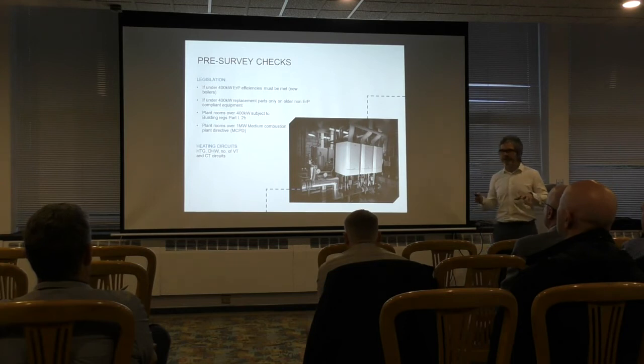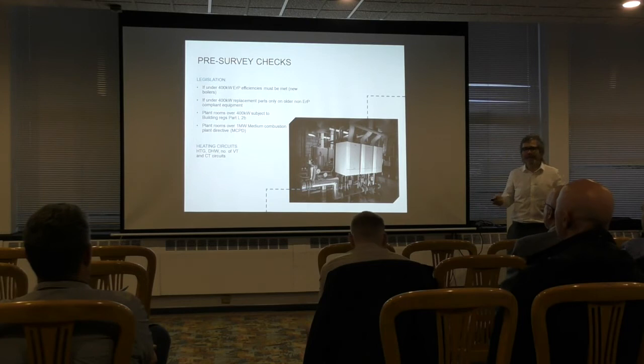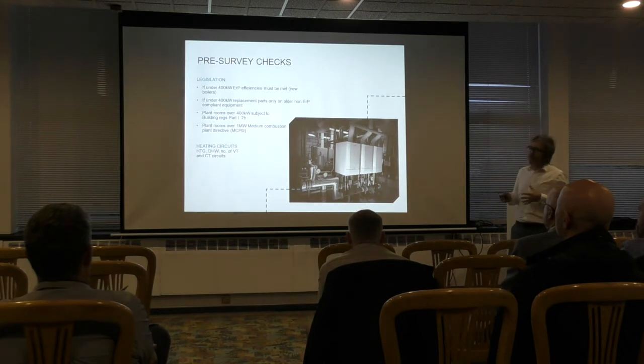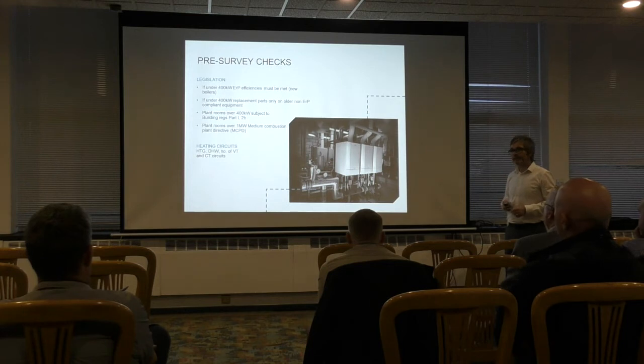Are you all familiar with ERP? Have you heard of ERP? If you don't know what ERP is, it stands for Energy Related Products. It was introduced really to the commercial market in September 2015. What it was basically saying is that any boiler under 400 kilowatts had to meet a certain efficiency. I can't remember exactly what it is, it's about 92.5% efficient, something like that.